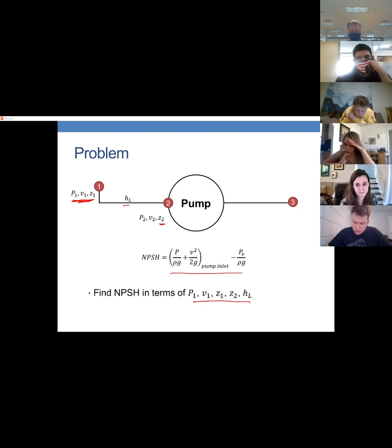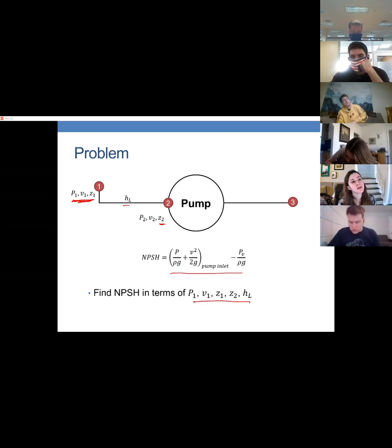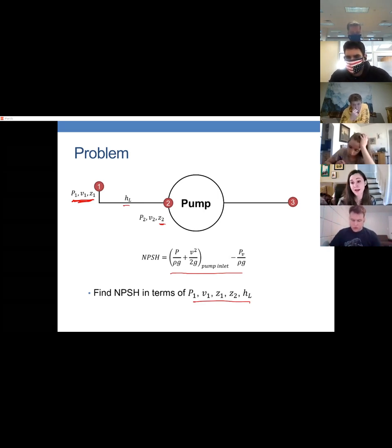Okay, this is another theoretical question. But yes, if your pump was weak enough to where it didn't increase the pressure that much and it never went above, even at the outlet, it wasn't above the vapor pressure, would any damage actually happen to the pump? So what you're asking is the pressure doesn't increase that much, and so maybe the, well, when a shock wave collapses, that's what happens when those bubbles collapse, it creates a shock wave, and shock waves go out in both directions. So my instinct is to say that yes, it would if cavitation happened after.